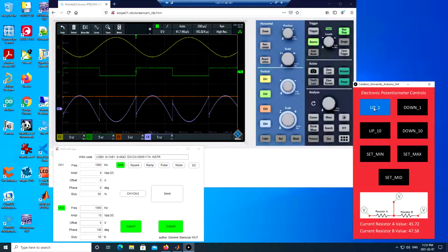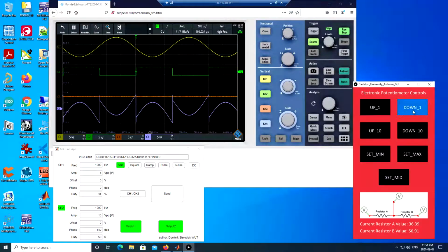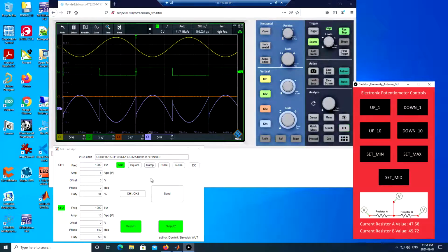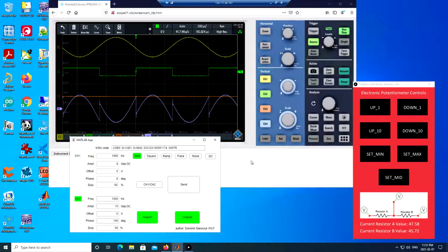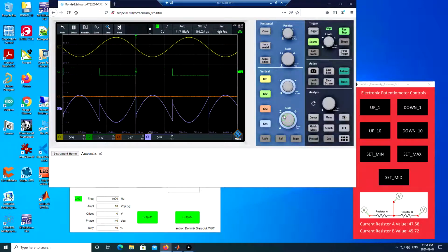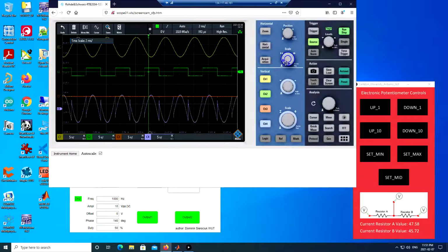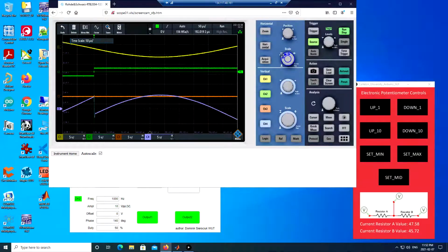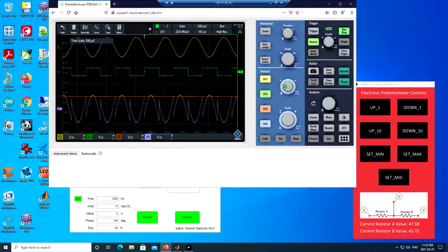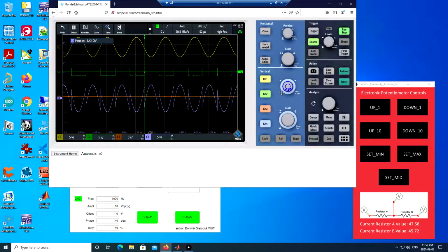So again, I suggest you go ahead and adjust the potentiometer to actually get a more balanced looking waveform here. It'll actually bring up and down your crests and crags a little bit, but that's fine. Again, we don't really care that it looks perfect. All we care is that you played around with this stuff and actually experience what the digital potentiometer does, experience what the actual function generator does, and actually how to play around with the scope's functions to maybe increase a channel's vertical scale, increase or decrease the horizontal scale to actually view different frequencies, and also using your up and down buttons to actually move your waveforms up and down on the screen.